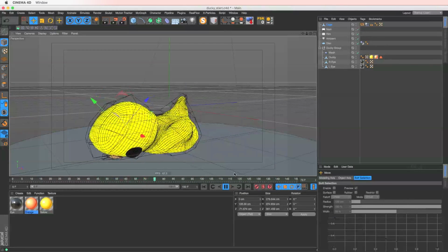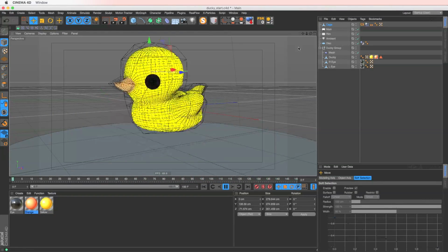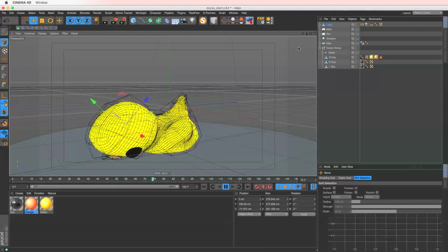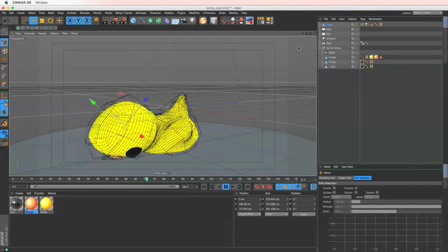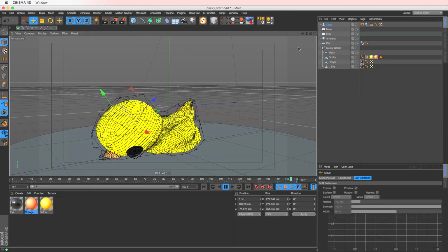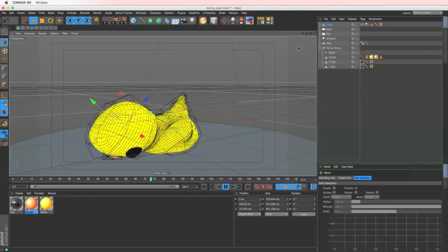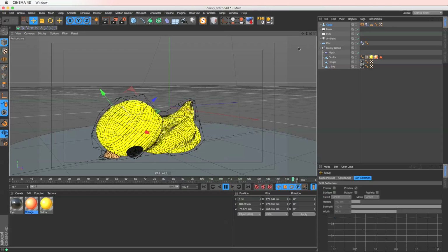Using a mesh deformer with a low poly mesh cage will really prevent any of those crazy issues from popping up, and it's going to speed up your dynamic simulation. So definitely use that. Use the mesh deformer, get to know it, make it be your best friend, and make some squishy rubber duckies. Alright, so hopefully we can inflate your brain with more knowledge of how you can try to get more out of your soft body dynamics by using the mesh deformer to make those crazy high poly object simulations a little bit more under control.